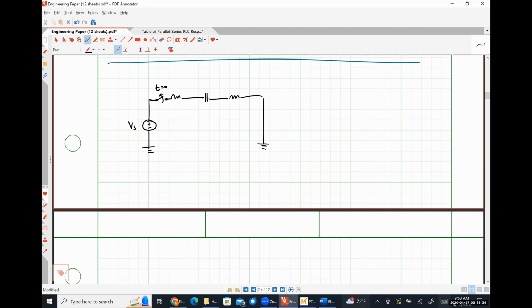So I don't think I've made any secret of the fact that I love guitars and everything guitar related. When you're servicing a tube amplifier, you actually have to use a special set of tools. Your screwdrivers have a wire that comes off of them to shunt things to ground, so that if you accidentally touch one of those capacitors, you don't kill yourself because of how much stored energy they have in them. So if you fully charge a large value capacitor and then you disconnect it, it will hold on to energy because it has nowhere else to go until you give it something to discharge to. So you better be safe on what you're discharging it to.